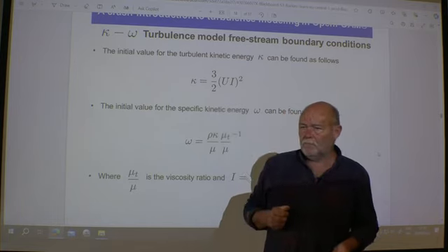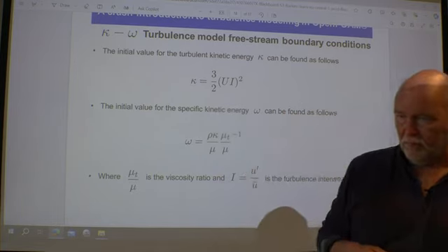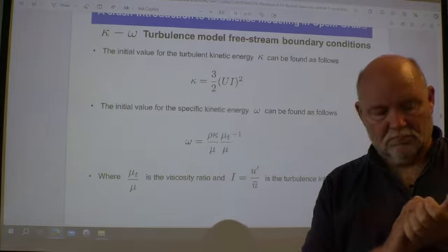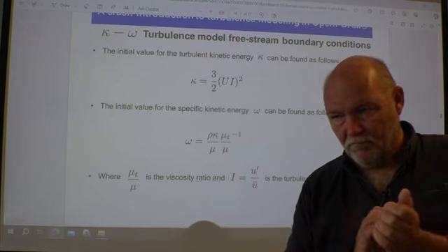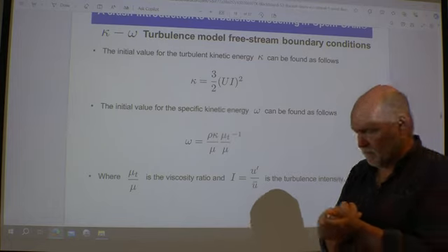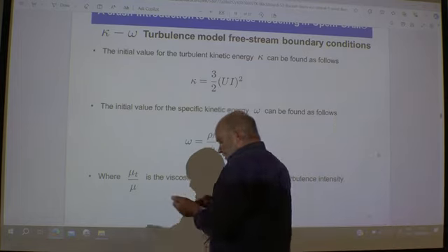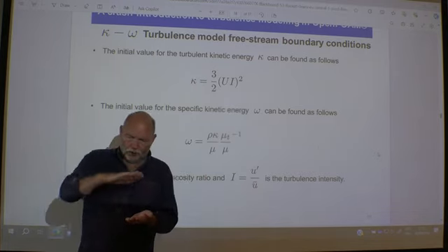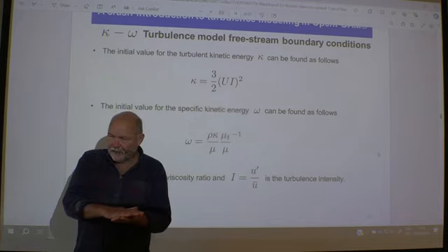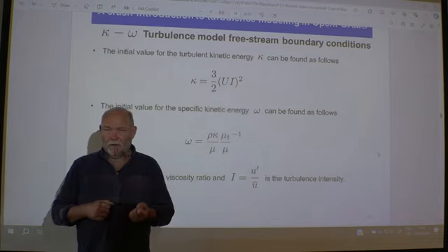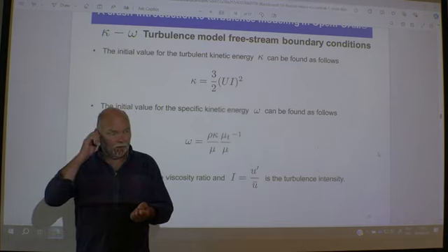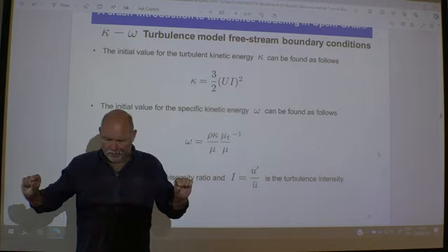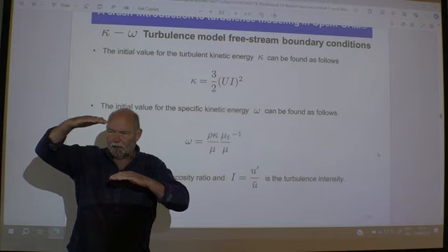When simulating a boundary layer using a really fine mesh instead of the wall function, is the refinement rate of the mesh cells relevant for the y+ values? Yeah, that's an important question. How can you resolve the boundary layer decently? So you might think that, okay, my first cell, very close to the wall, I take that one very, very small. Then the next cell, well, he's rather big.